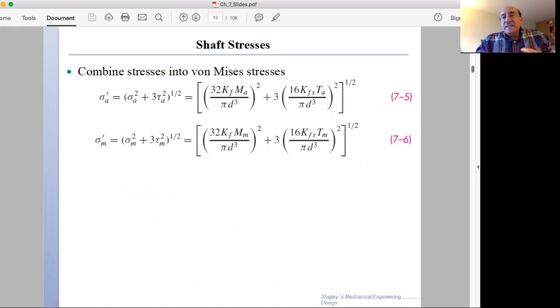So for shaft design, we start from forces, we find moments, we find torques, and then we are able to find stresses. This is step number 1. Step number 2, we must apply fatigue factors to the material. So we have one column that's the material, one column is the forces leading to stresses. So I have forces, moments, torques, and stress concentration factors. This is one calculation.